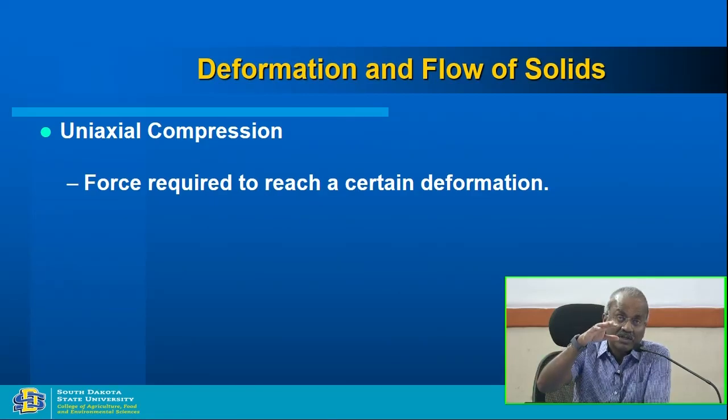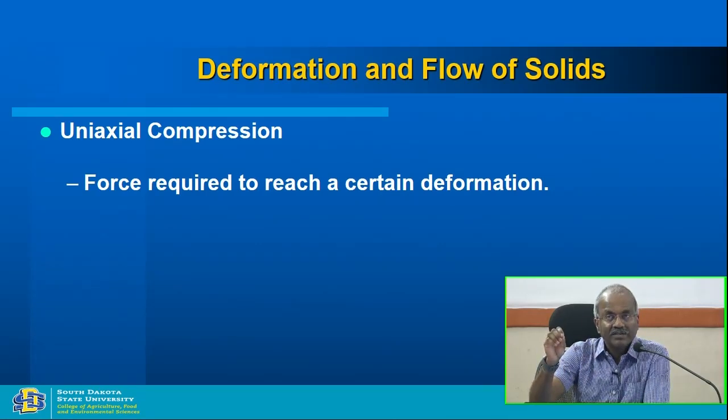You do not apply the force and then measure the deformation. You deform the material and simultaneously you also measure the force you apply as you deform the material. And that is the data you collect, force with respect to deformation.